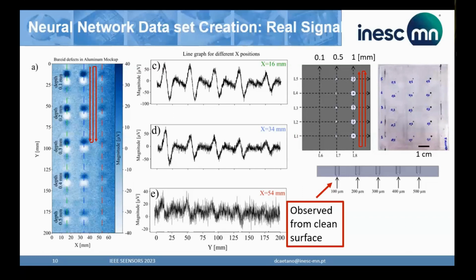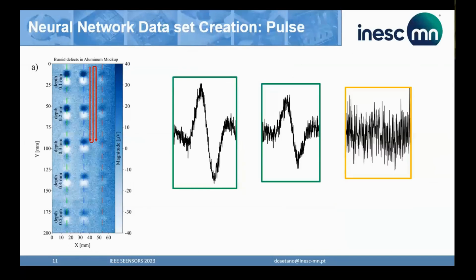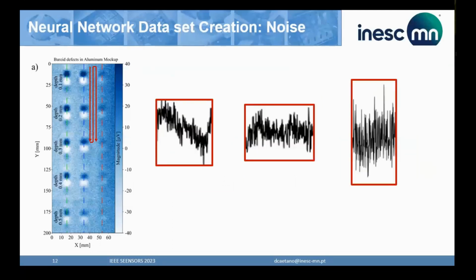I wanted to analyze the 1D signal. You can see clearly that this is relatively easy to detect, not so much here, and here, where we know there is a defect, but it's practically impossible to see. So if you analyze the problem as a binary classification, this would be class 1, what we want to find, and noise would be class 2.